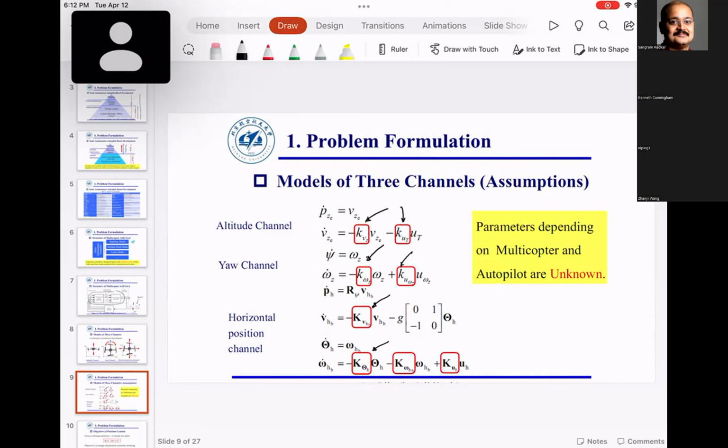The other thing, you also have sensors. Many times, the data coming from sensors is at a much lower rate than your PID control loop. So what you want to do is a rate adjustment.